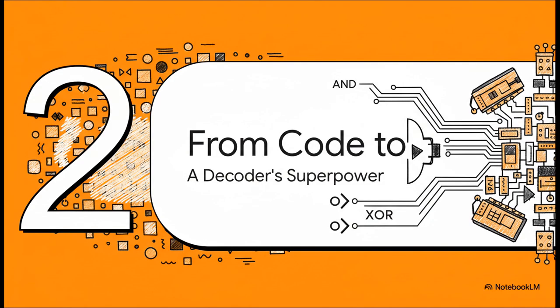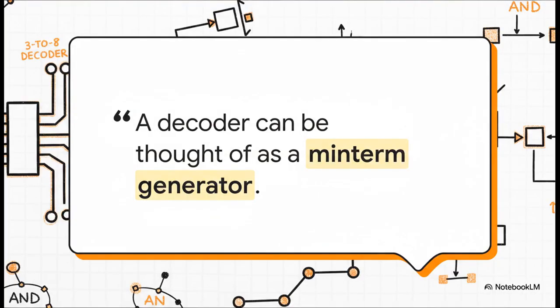So being able to pick one thing out of many is super useful, for sure. But that's not the whole story, not even close. This simple function is hiding an absolutely incredible superpower that lets us build almost anything we want. This right here, this is the secret. Every single output line from a decoder perfectly matches one specific combination of its inputs. And in the world of Boolean algebra, we call each of those unique combinations a minterm. So a 3 to 8 decoder doesn't just have 8 outputs, it's really an engine that can generate all 8 possible minterms for 3 variables.